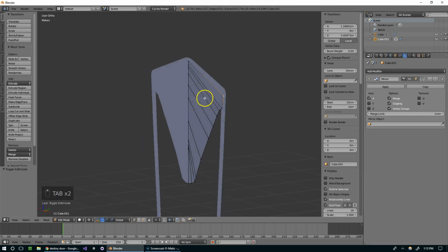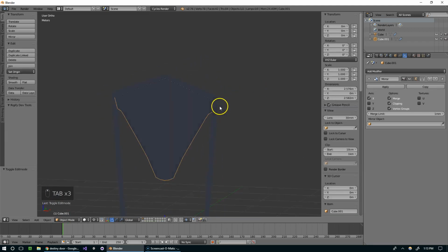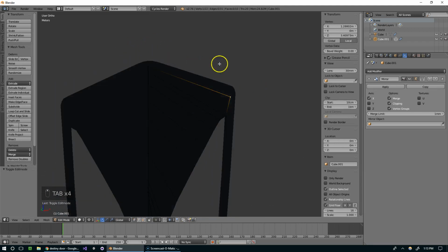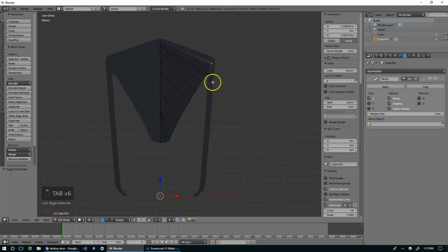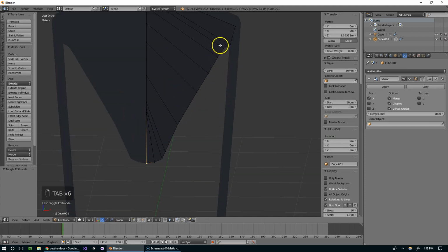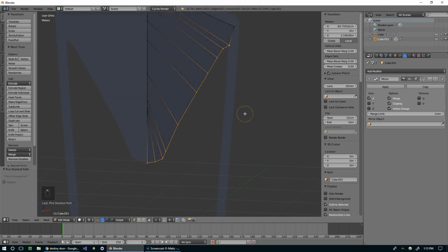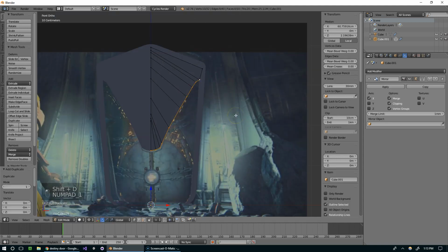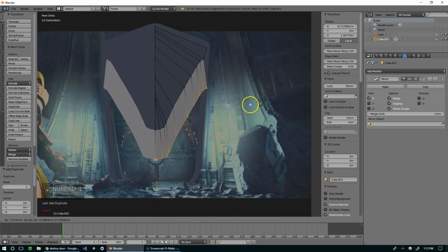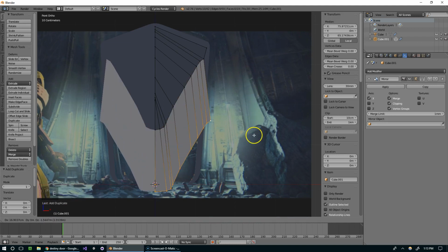Alright, so we have the whole top of the door now. And there's a little bit of weird overlap there, but we can deal with that later. So now we can create the bottom door. So I'm going to grab this point, Control right click up here to get those, Shift D to duplicate, 1 for front view, and then E to move these down.